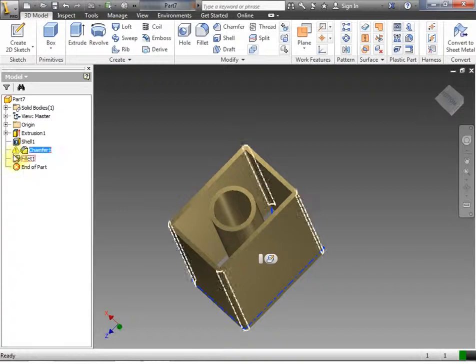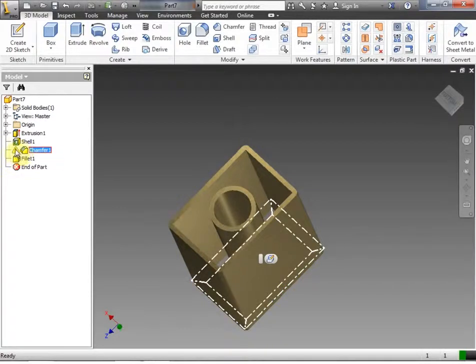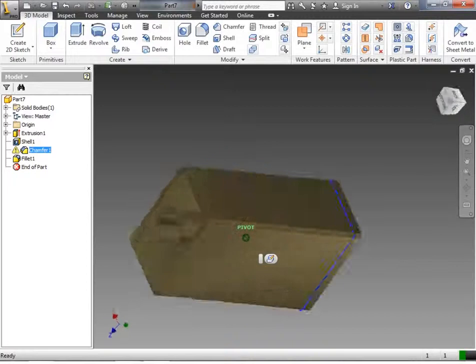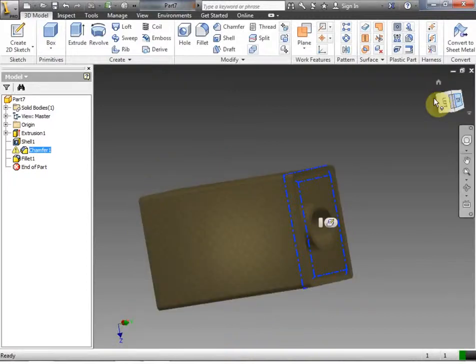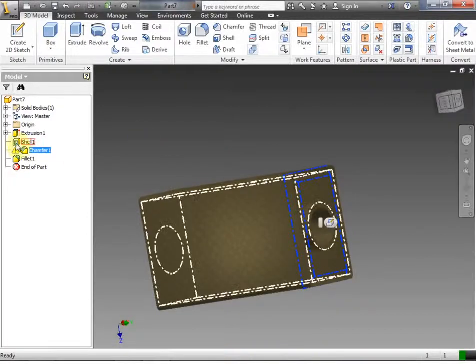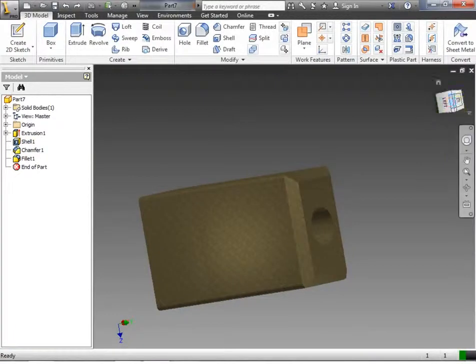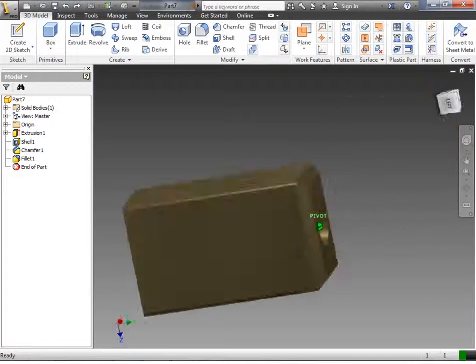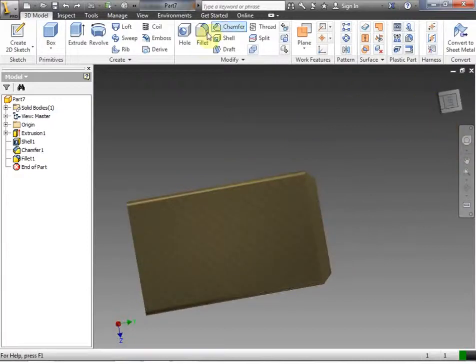You'll notice this, and if you see this in your drawings, do you see this little caution sign right here, this little yellow triangle with an exclamation point inside of it? Basically that's saying that feature, that 3D feature, did not work and has been removed from the drawing. So what we could do is we could go ahead and Control Z, and basically that will get us back to our original thing. Okay, so those are the shell, chamfer, and fillet tools.